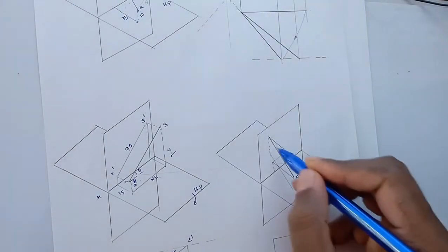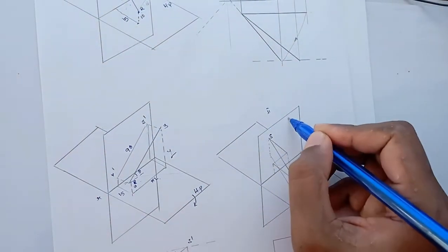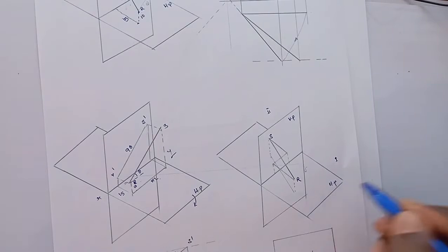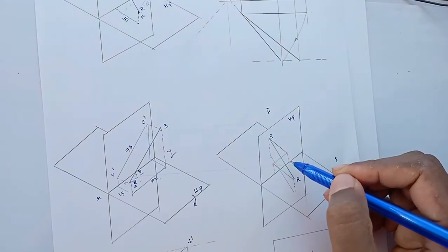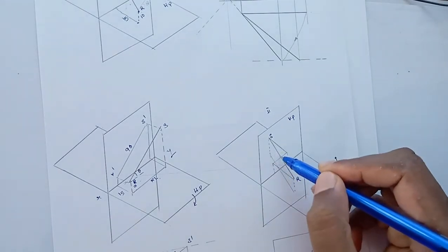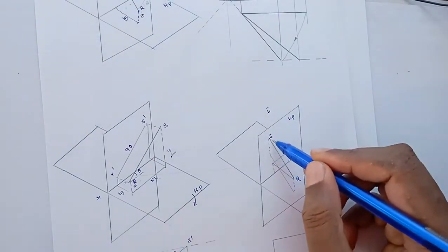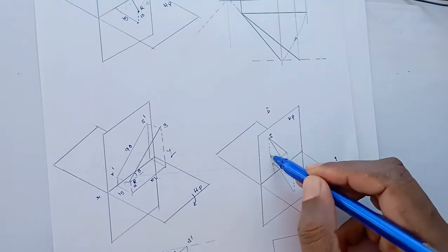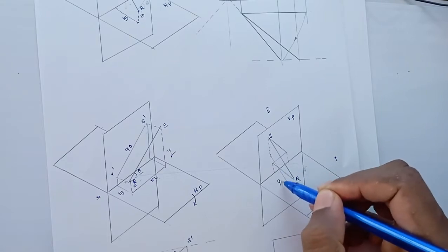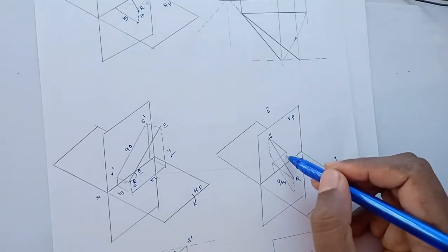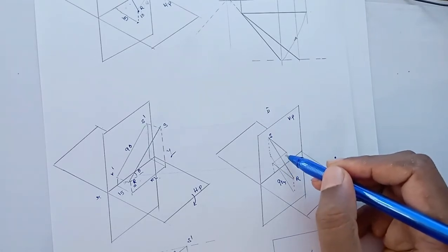So after rotating the line, we can get the figure like this. This is our line RS, and this is our first quadrant, second quadrant, this is VP vertical plane, this is HP. And after making the line parallel to HP, we can get a front view like this, and we will get a top view like this. So the top view will be in true length because the line is parallel to HP, and this is the projection of the top line. This is the top view. This is 90 mm. And what about this length? We don't know the length, but we can find it out from this figure.